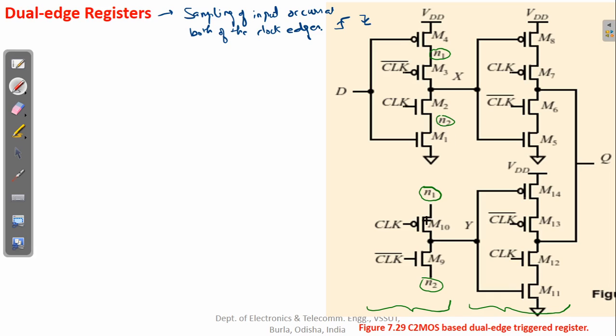Okay, so it means that above this M10, which is a PMOS transistor, there is one more PMOS transistor, and then there is a connection to VDD, and below this NMOS transistor there is one more NMOS transistor, and then ground is present there. Okay, and there would be an application of input signal to these upper and lower transistors, like this is done here.